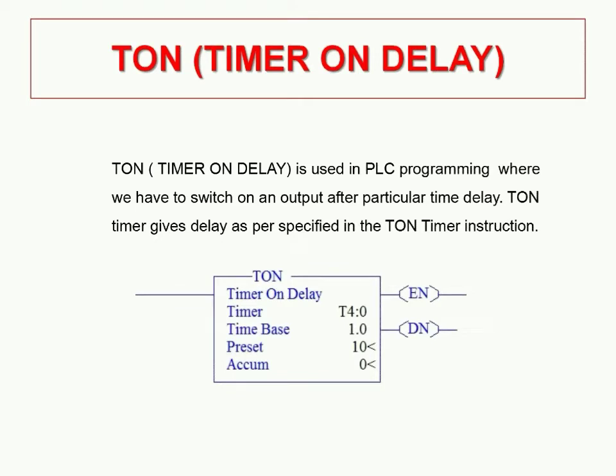Timer on delay is generally used as you can see in the description on your screen. Apart from this, I would like to explain in layman language what a T-on timer is. A T-on timer gives delay in on time. In my earlier video tutorials, what we were doing is that we used to switch on the input and we get the output. But now we want to get the output after a particular time. Suppose we want to give delay in starting a motor or a pump. So the pump and motor are the output.